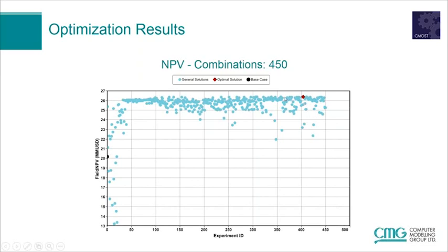And in this study, we did about 450 runs, but you can see here that even after slightly less than 50, CMOST came up with a fairly good optimum. So I mean, if your run times are longer, you don't necessarily need to do 450 runs. You might do much less and still come up with a good optimum.